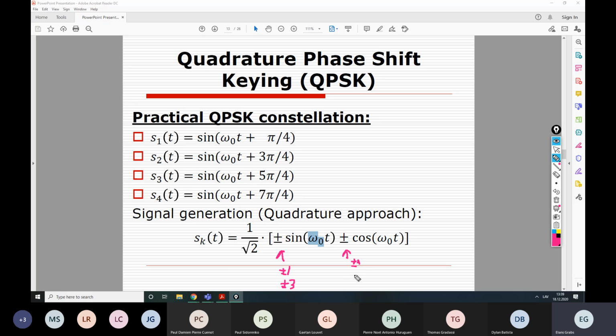Different amplitude. So that's why it also is called quadrature amplitude shift keying. That's how this A letter came in the name of the modulation type, because basically it's still quadrature modulation, but now it also changes amplitude.